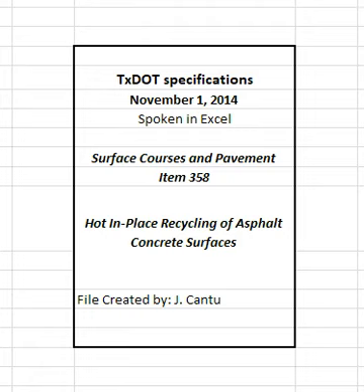4.10 Curing. A surface treatment may be allowed as the final riding surface when shown on the plans. Cure the hot in-place recycled bituminous material for a minimum of 7 days, or as directed, when HMA or another applicable surface treatment is placed as a surface course.